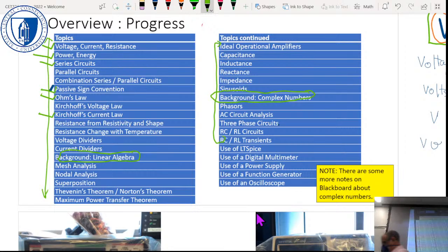All of those holes are connected together electrically. All of the holes down the blue line, just beside the red line, the line of red and the line of blue are not connected together electrically. So normally, the red line is for the plus side of the voltage supply, and the blue line is for the minus or the zero side.